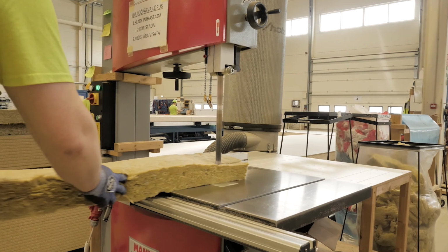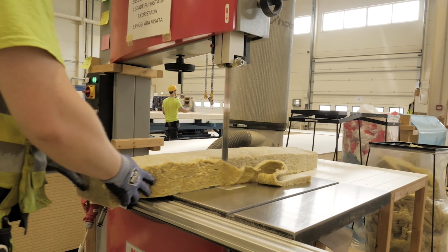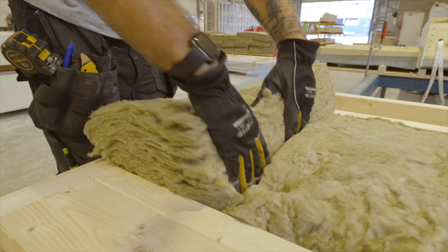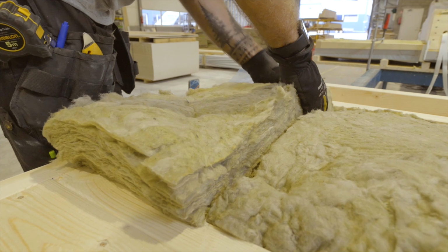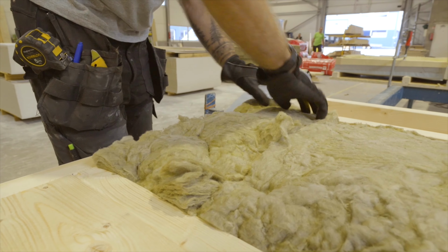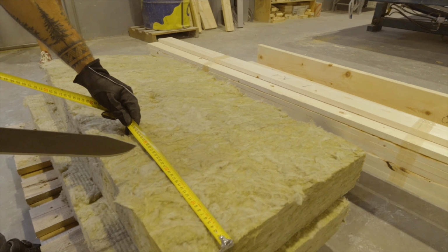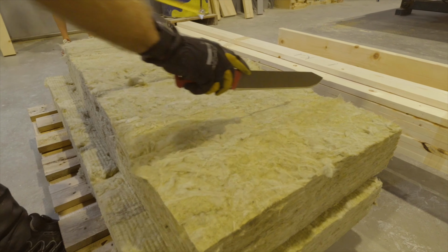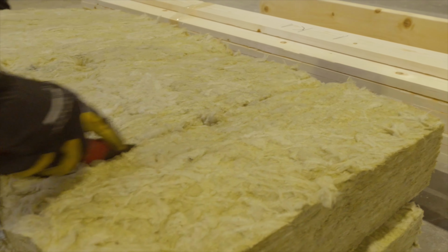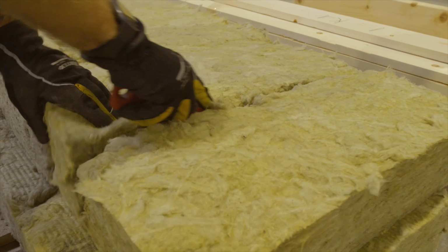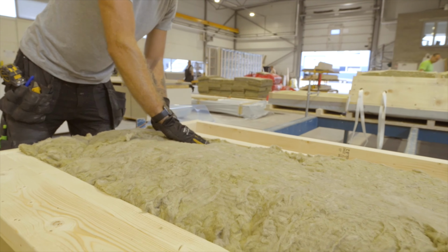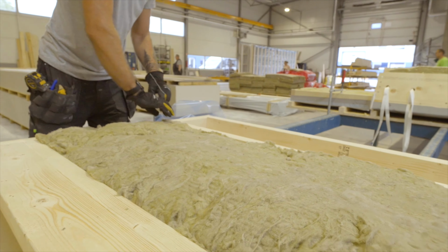As with any material, insulation needs to be cut to the correct size according to the project. For optimal insulation of the element, the insulation material should fill all the space provided for it, leaving no gaps. In general, the dimensions of the insulating material are 5 to 10 mm larger than the filling hole to fit snugly against the structure. In order for the insulation to correctly perform its function, it is necessary to avoid the